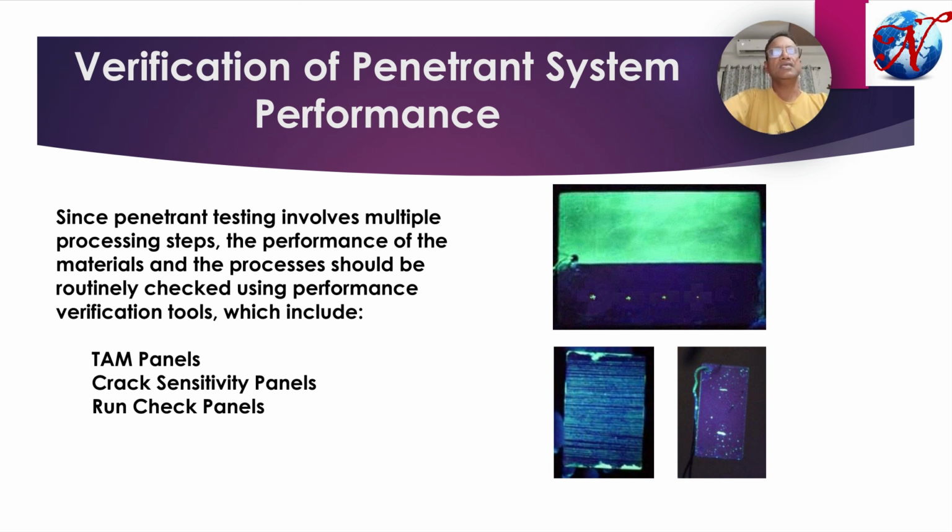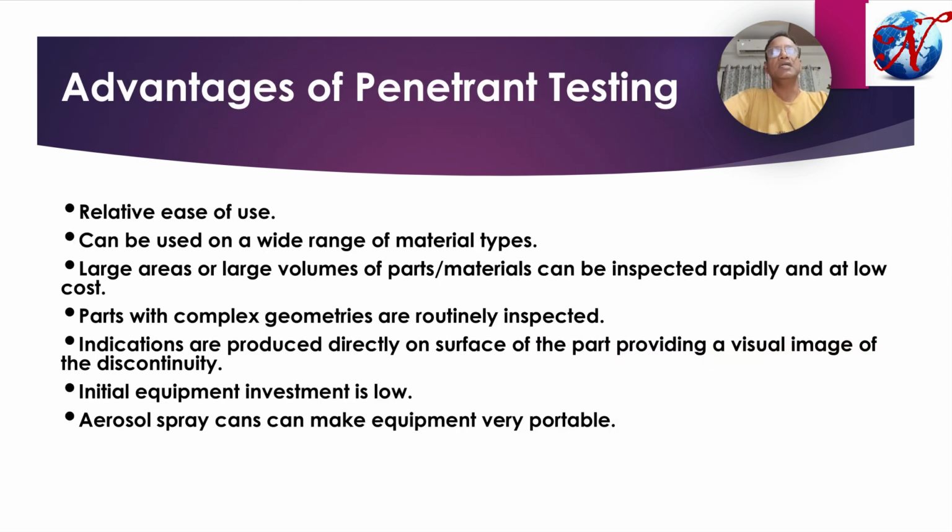Liquid penetrant testing has a lot of advantages because it is relatively easy to use. The initial equipment investment, costing, training and developing the interpretation skill are not very difficult. We are using portable equipment, so in areas where accessibility is a concern, we can easily carry the small portable tanks, and we can collect information on the spot.